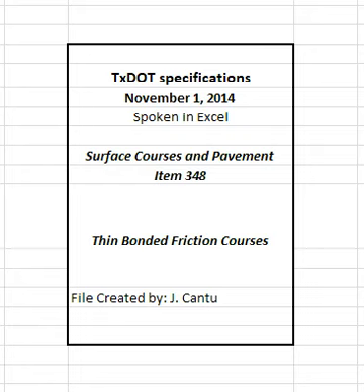4.7.2 Application of membrane. Apply the membrane at the rates shown in Table 9 unless otherwise directed. Spray the membrane using a metered mechanical pressure spray bar at a temperature of 140 degrees Fahrenheit to 180 degrees Fahrenheit. Monitor the membrane application rate and make adjustments to the rate when needed or when directed. Verify that the spray bar, if required, is capable of applying the membrane at a uniform rate across the entire paving width as directed. Do not let the wheels or other parts of the paving machine contact the freshly applied membrane. Table 10. See table in specifications.